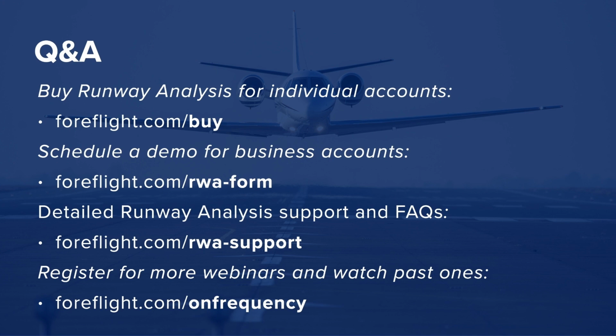So if you make a change to the weight, that is passengers, cargo, fuel, assuming we're talking individual account here, any changes that are made on that flight are synced across all of your iOS devices. So said another way, if I'm using my iPhone and I decide to increase my fuel or add a passenger, that weight change is going to sync to my iPad as well. And that data is used in our takeoff and landing configuration to calculate the baseline numbers that we come up with.